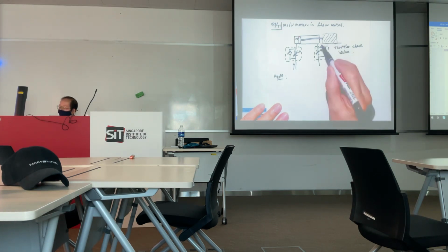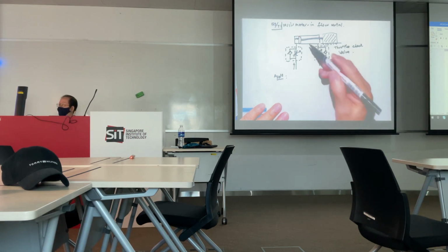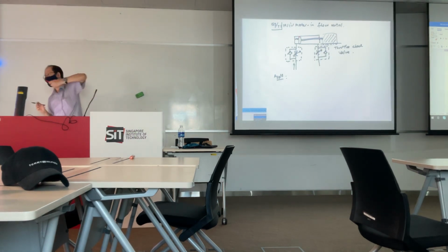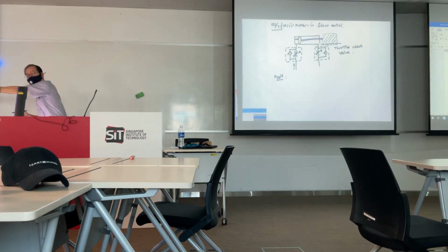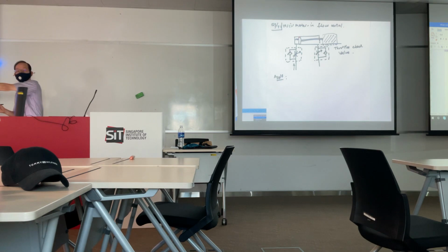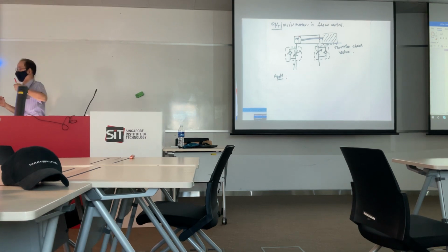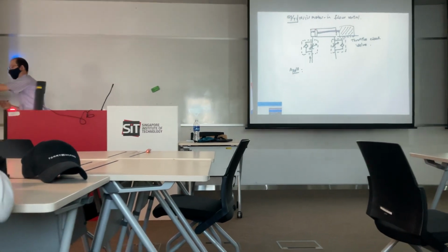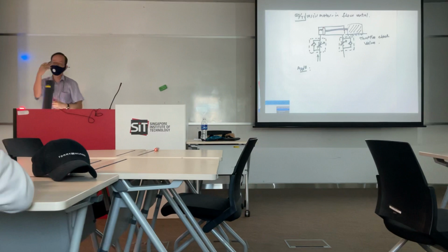There's some frictional resistance as the cylinder goes forward, so in this case, it's okay. It's pushing a load. If it's not pushing a load, or pushing even a very small, very light load, it can also jerk. So the resisting force must be considerable. If it's a small load and you get a hydraulic cylinder to push it, then it might jerk because there's no resisting force.